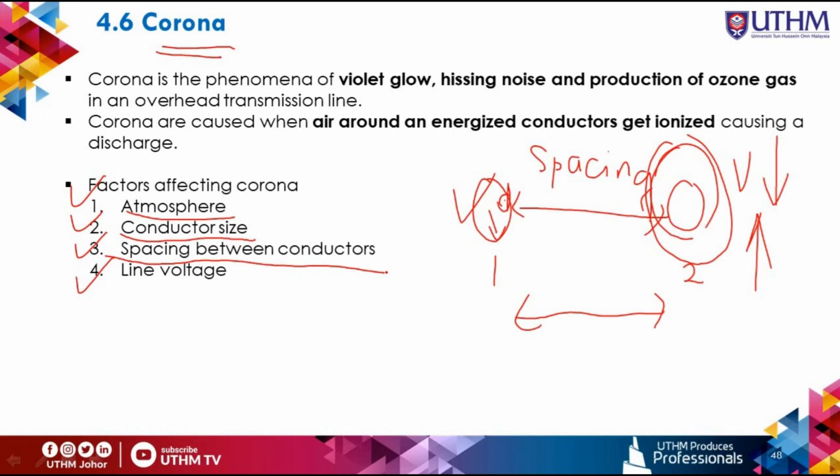The third one is the spacing between the conductors. If the spacing between the conductors is made very large as compared to their diameters, there may not be any corona effect, because a larger distance between conductors reduces the electrostatic stresses at the conductor surface, thus avoiding corona formation.